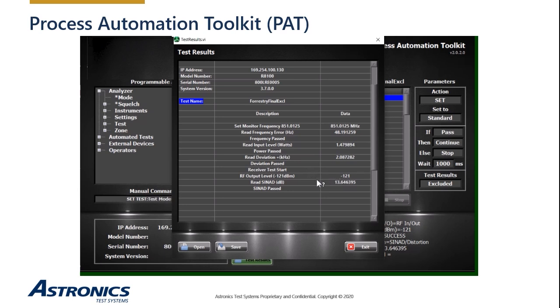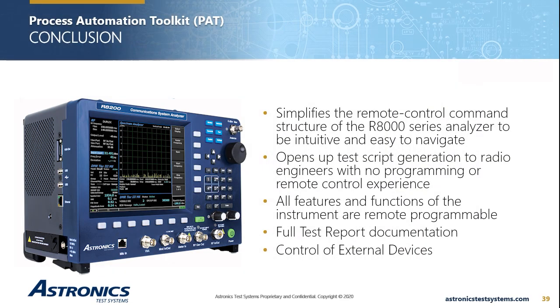During the presentation we have learned how simple and intuitive PAT is to write your own test scripts. No programming knowledge or experience is required. If you know how to make the test on your DUT radio manually, PAT can automate it. PAT includes all the commands that emulate manual operation of the R8000 series. PAT generates full test reports that are saved in .csv format for archiving.